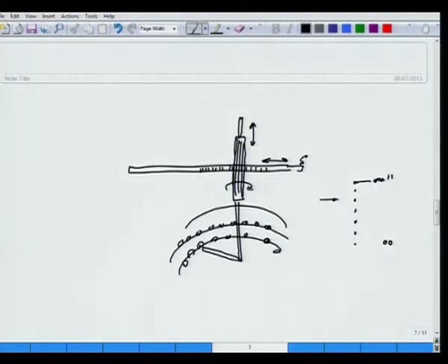And of course, there are many control circuits which are built using relays, and these are integrated with these kinds of things. Okay. He also started what we call the concept of common control switches. In this case, the control circuitry is common, and is used for different uniselectors and 2 motion selectors at different points of time depending on requirement. It is not all the time. So common control switches were slightly complex, but the amount of hardware required is small.